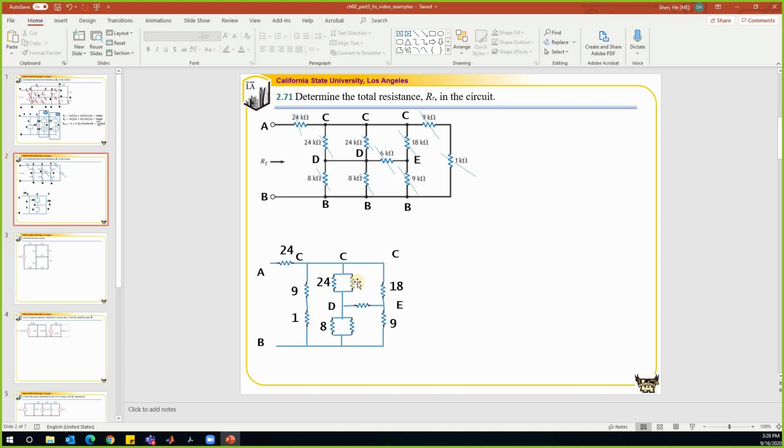That's very easy. But over here, look, this is three resistors. I'm looking at these two as one equivalent resistor. So 1, 2, and 3 resistors. And these three resistors form a delta-shaped network. This is the delta-shaped network over here, and we need to replace that by the Y-shaped network. We can further simplify it, right?